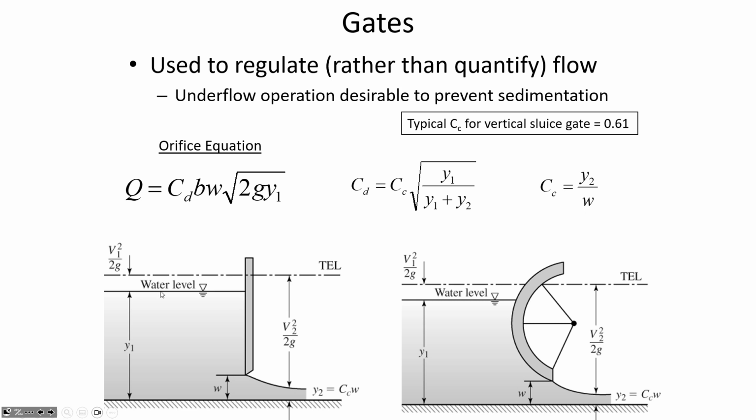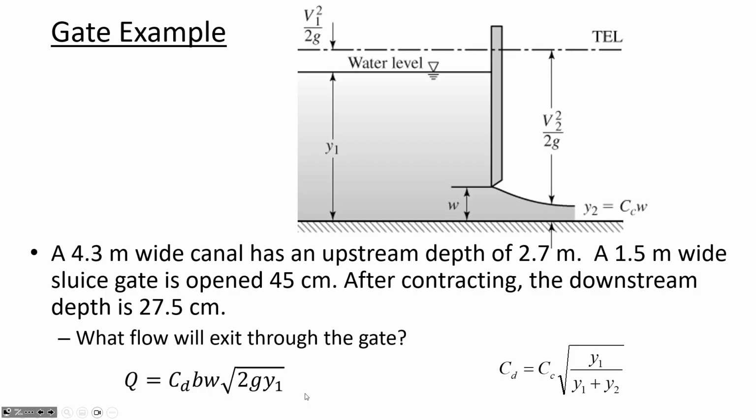But here, just for simplicity, rather than measuring from the center line of the opening, we measure all the way from the bottom of the channel and upward, and then we could factor in any variation into the discharge coefficient. So the orifice equation is how we find out how high of a water depth upstream predicts a certain flow rate. And so let's get some practice with this.